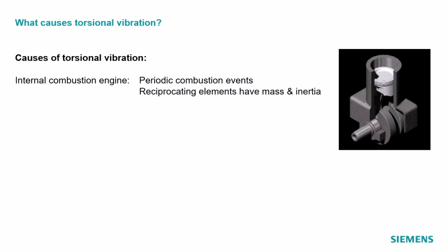I guess you can understand a combustion engine isn't necessarily going to run at a constant speed because of the motion of the piston. Not only that, there's a firing event. That's that little star there I'm drawing on the top. That's where the spark plug might be. Actually, it's over here, the gap on that spark plug. It ignites the air-fuel mixture, and when it does that, it throws that piston down violently. So the combustion event itself also causes it to speed up and slow down.